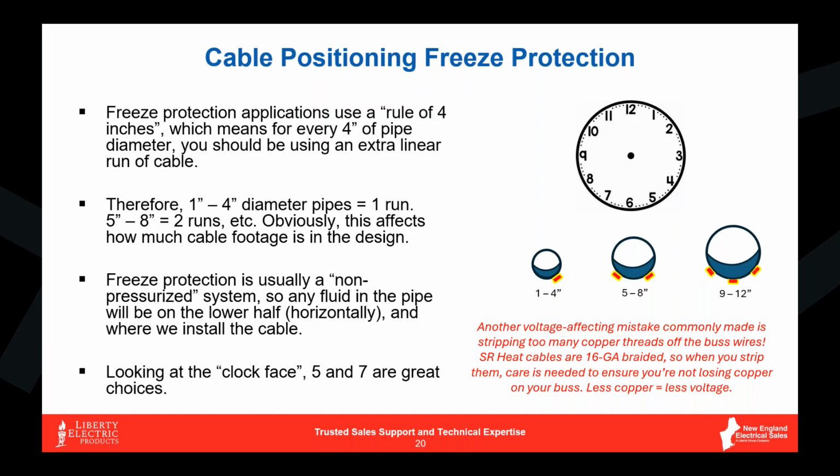So you can only imagine, if you've got an electric heating cable that's been sitting saturated in a wet sponge for, I don't know, 6 or 8 months, there is a distinct possibility that at some point moisture might actually be able to find its way in. So generally we got away from putting it directly at the lowest point on the pipe and changed it to 5 or 7 o'clock, if that makes sense. Again, it seems like a pretty common-sense thing, but until you have somebody out there who's done this before and knows these little tips and tricks, it can be easily overlooked.